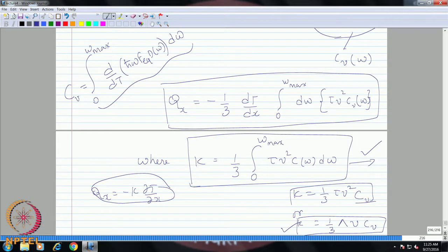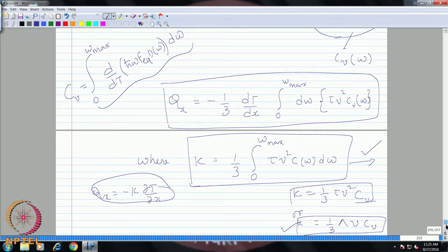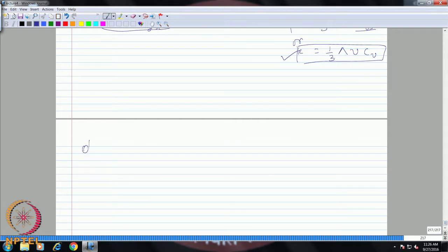So, in the subcontinuum we do not have to define a property like conductivity. Okay. So, it is all a function of the phonon velocity, relaxation time, heat capacity and so on, but we can relate all this to the thermophysical property called conductivity, and therefore, we can say that this is your Fourier's law, correct. This is a very useful way of deducing many constitutive relations. So, not only the Fourier's law, but we can also do this, for example, to deduce the Ohm's law. Okay. So, maybe to just give you another example, let me do this also for the charge flux similar to the heat flux here. So, the electron charge flux. So, we will also now use this to derive the Ohm's law.